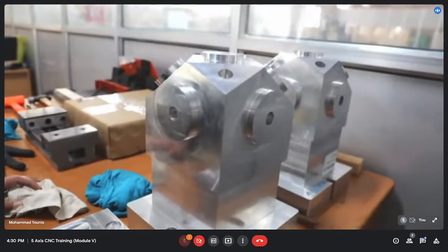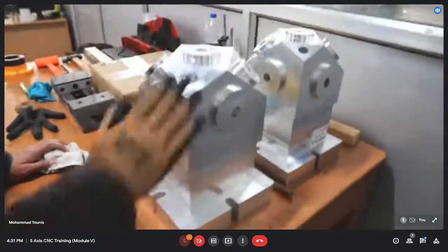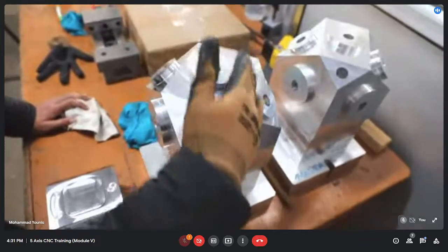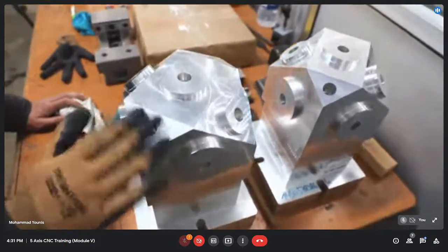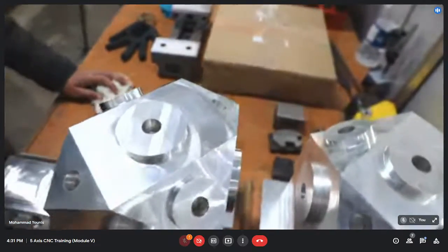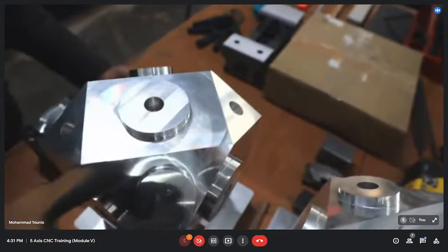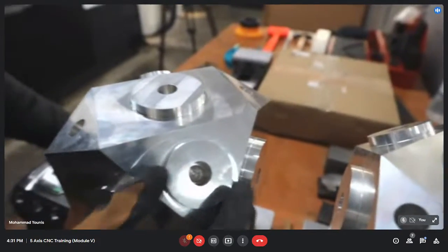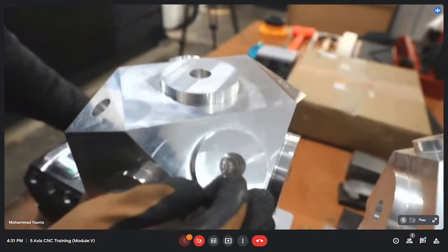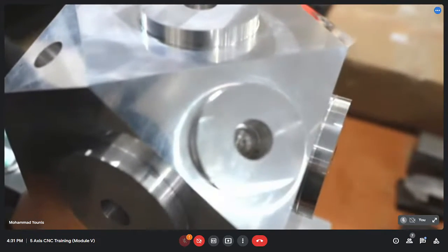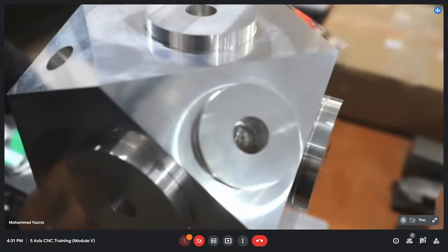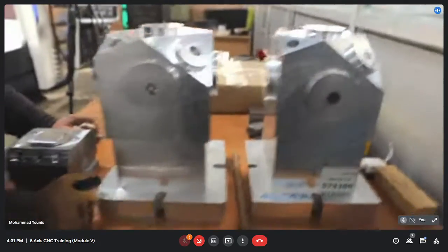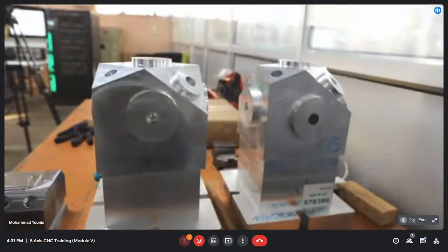Okay, and also here we have machined these corners at some angle. You can see here, we have machined the corners. We have provided chamfers. I think this is a 45-degree angle, and we have performed other operations like we have drilled a hole here. Then we have enlarged that hole, and we also have performed a finishing operation with a boring tool, and this is done for all other spigots as well.